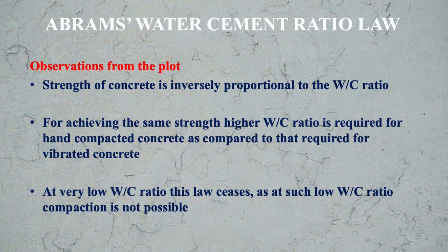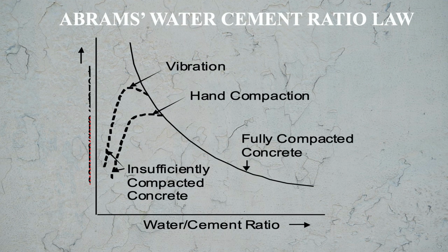At very low water cement ratio, this law ceases as at such low water cement ratio, compaction is not possible. In the initial portion, you see that when the water cement ratio is very low, the solid line is missing. For the very initial portion of water cement ratio, there is no solid line there. Means it indicates that here the Abraham's law does not exist. It ceases to exist. So thank you for watching.